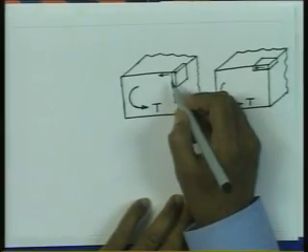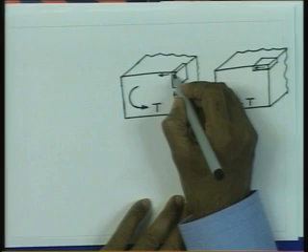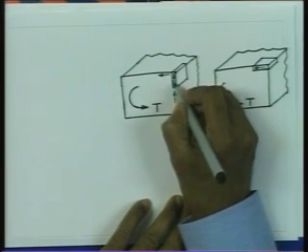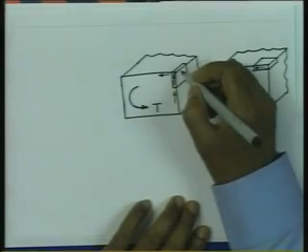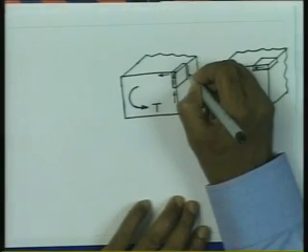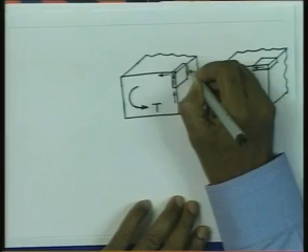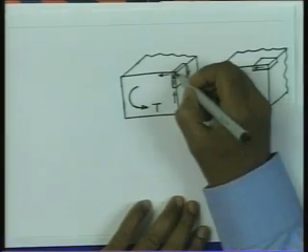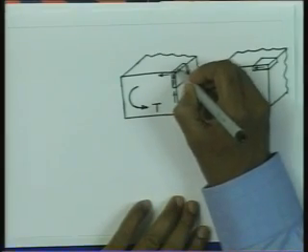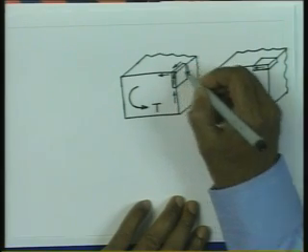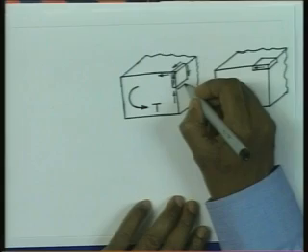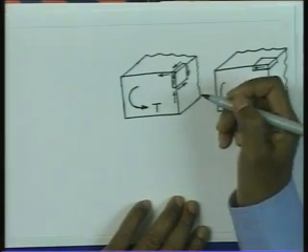Now, I will give you the third way of finding out the stress to be 0. Let us concentrate again on this element. If the stress is going to be acting on this element on this face like this, then the stress which is going to act on this face, the opposite face, it is going to be like that, and the complementary shear stress will develop on the top surface, its direction has got to be like this. Similarly, on the opposite face, the stress direction is going to be like this.